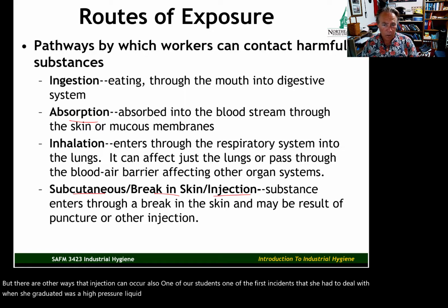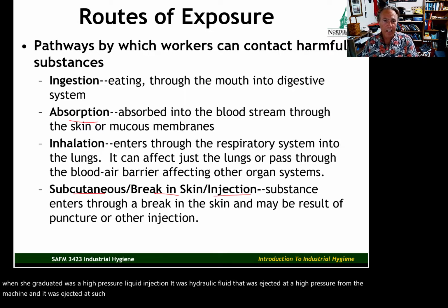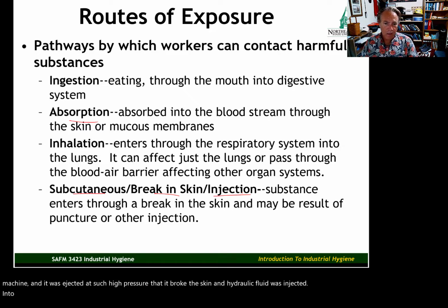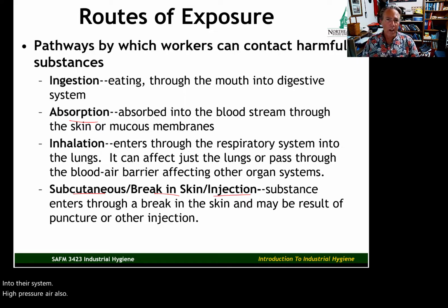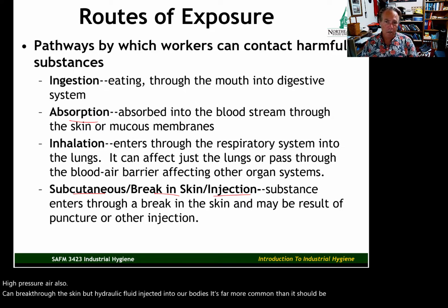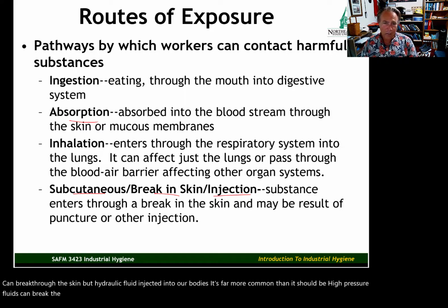It was hydraulic fluid that was ejected at a high pressure from the machine, and it was ejected at such high pressure that it broke the skin, and hydraulic fluid was injected into their system. High pressure air also can break through the skin, but hydraulic fluid injected into our bodies is far more common than it should be. High pressure fluids can break the skin and enter our bodies in that way.